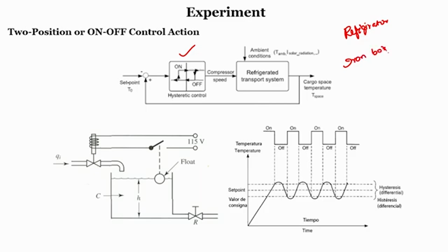When I say automatic iron boxes, that has a bimetallic strip which acts as an actuator. A bimetallic strip is made up of two dissimilar metals joined together. Because of the different properties of the two materials, the expansion coefficients will be completely different. Because of that expansion, it bends in one direction. As a result, the switch will be on or off. Such an actuating system can also be used as an on off controller in such applications, to switch your system on or off.